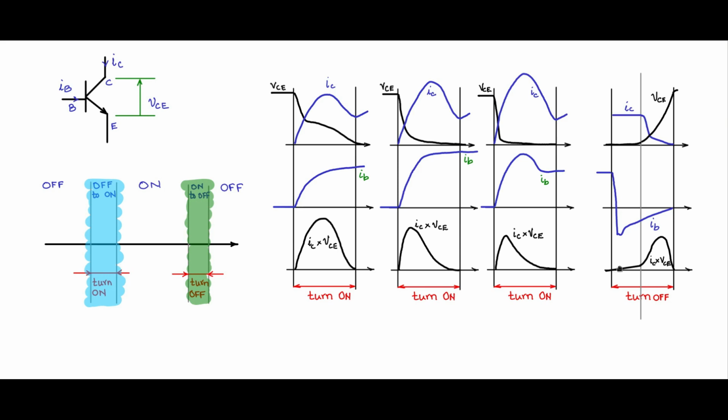During the first portion of the turn-off period, which we call TS or the storage period, you will not see much change in IC and VC because the base charges are in the process of getting removed, and the majority will get removed at the end of the storage time.